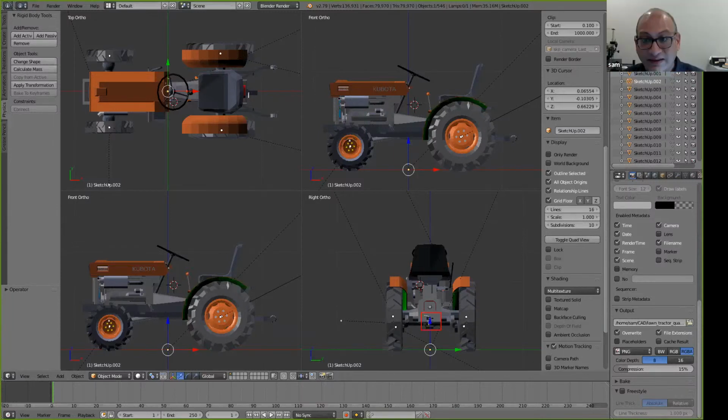So let's say, for example, I have a square, like a rectangular box, that I just drew. If I have to make everything right, I will put my X, Y, and Z origin, transformed to right at the rear of the axle, and make sure that I also align the x-axis to the front. I would do that translation and rotation right in the CAD data, and then bring it in at 0, 0, 0. And then you don't have to change anything.